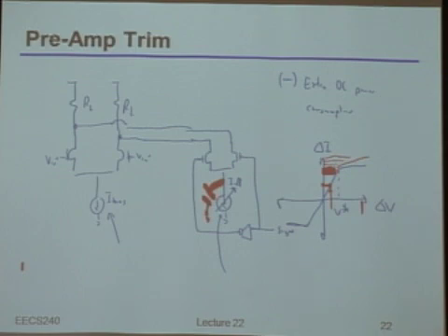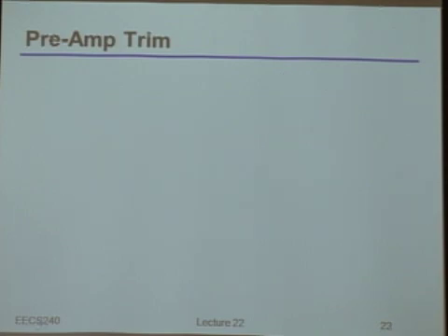Okay. So as I said, this does have some limitations, but it is kind of my own personal default solution because it has a lot of nice characteristics. Having said that, there are some other tricks that people have come up with that try to address the issue of being forced to spend extra power just to cancel a DC offset. The basic idea is to say, let me build a circuit that will always use whatever DC current I have to give me some transconductance, but do it in a way that I can program the offset.